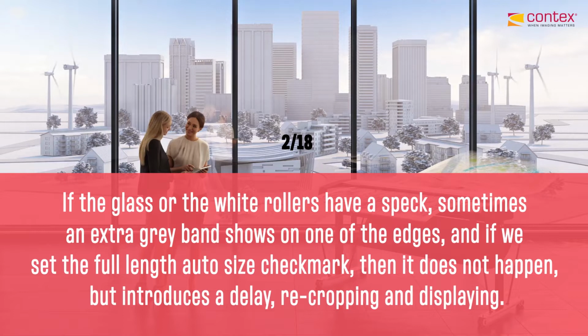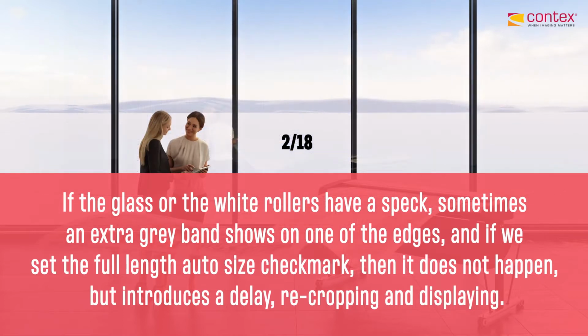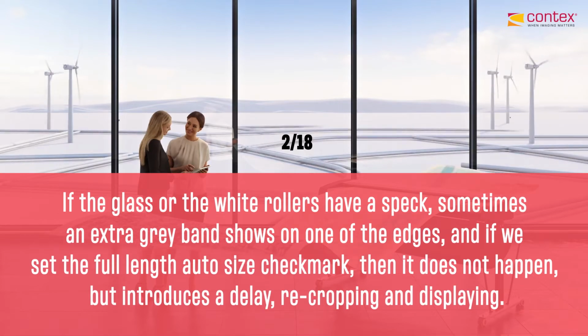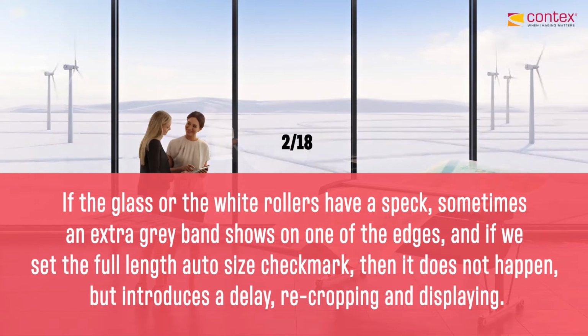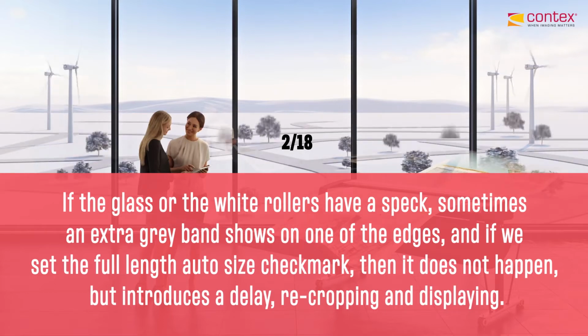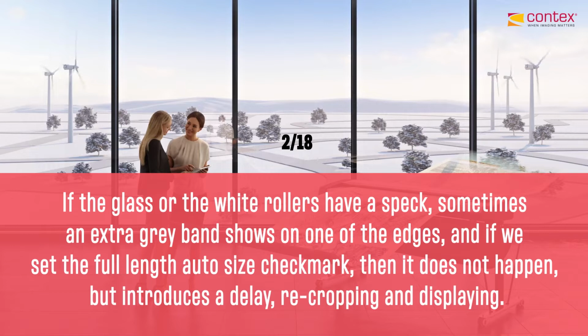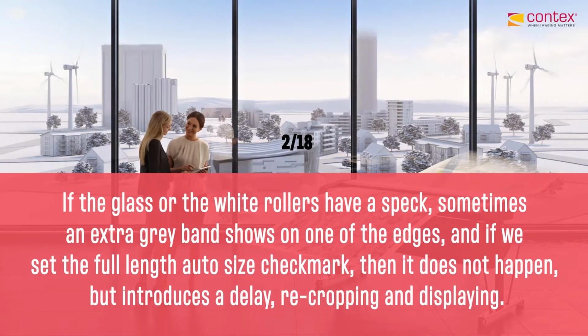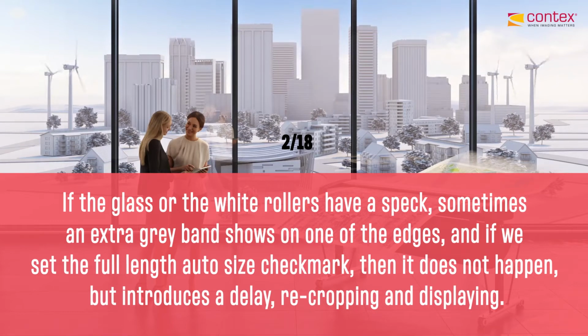And when looking for these things, you've got to remember the scanner, if it's a 1200 optical resolution scanner, that noise can literally be a 1200th of an inch in diameter, but if it falls right where the scan line is across the glass plate, then it's going to see it very dark, and it could make a mistake and use it instead of the actual paper edge as the auto size, as the sheet size.